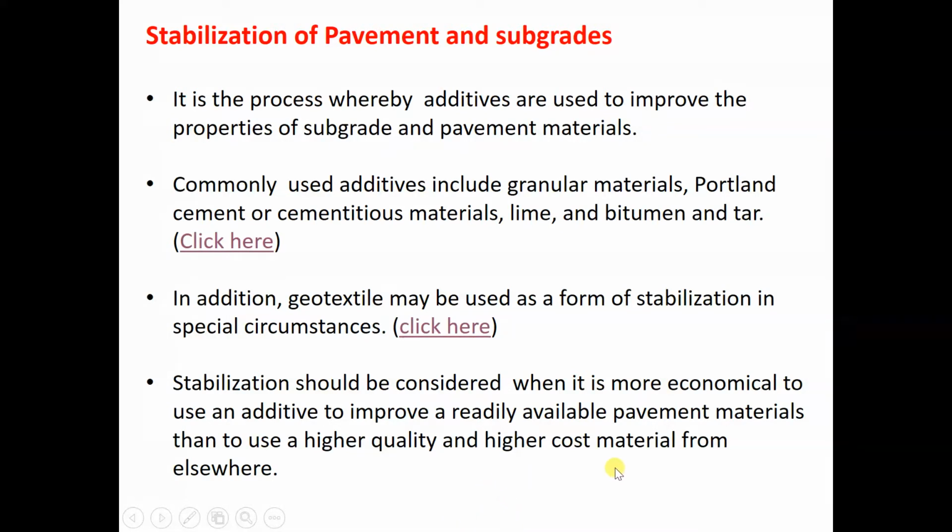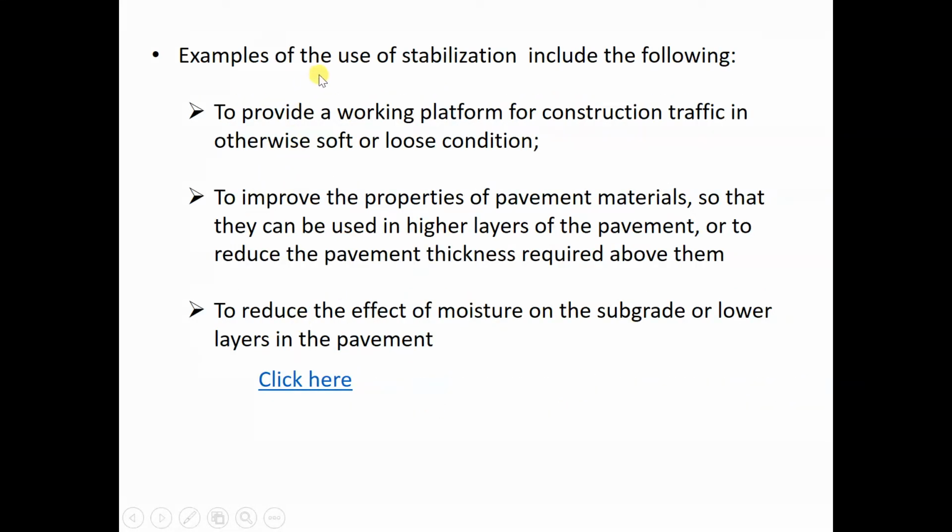Sometimes we need to, sometimes we don't, and a lot of the time the reason is because of the economics. Because if we can achieve the same strength of the pavement by stabilization and with a lower cost, then stabilization could be the way to go forward.